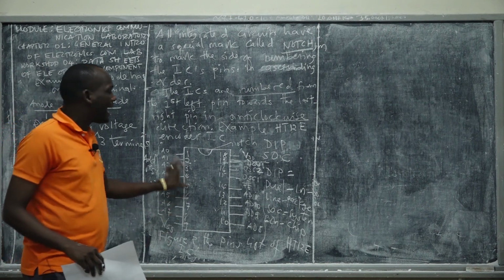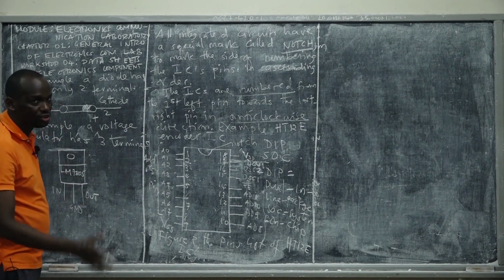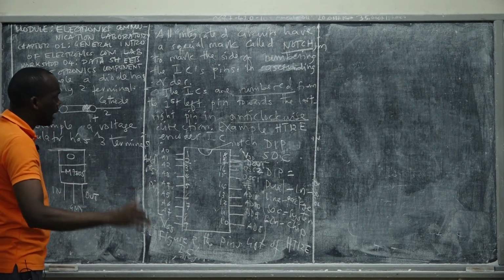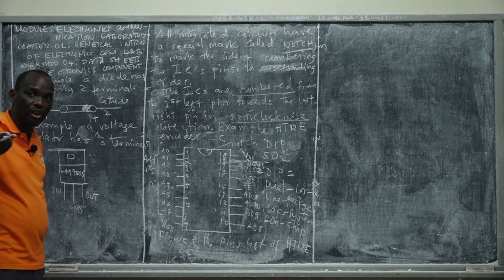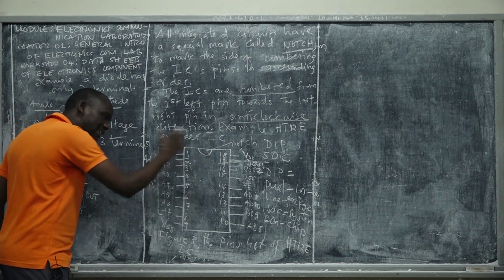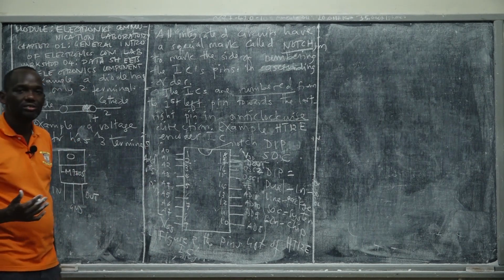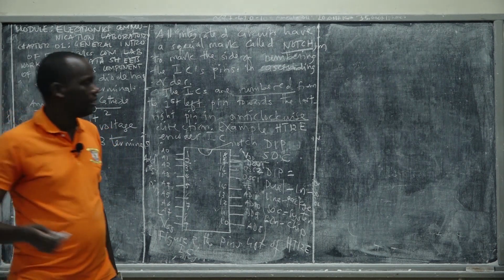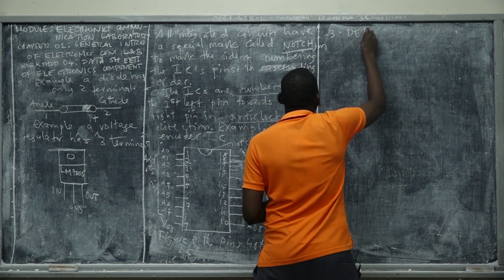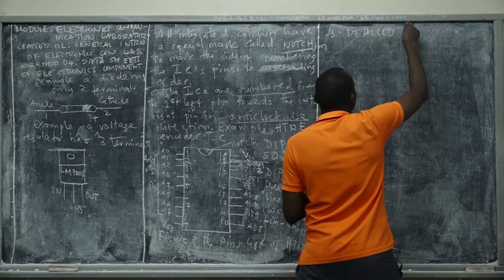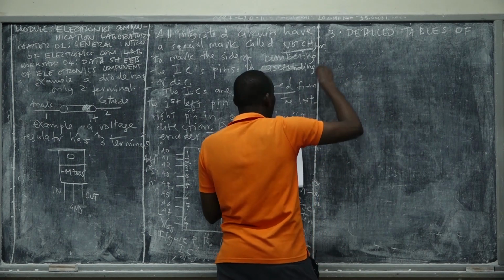Okay, so that is all about what? Because we'll be discussing this encoder later on, I don't want to touch the functions of these address pins, and we'll discuss them. We have a number of workshops discussing that. But simply remember that in this pin assignment, first you'll see the packaging of that IC. Number 2, you'll see pin numbering according to the manufacturer. Number 3, you'll see pin naming. Number 4, you'll see also the function of each pin. Are we together? Yeah. Then the next part is called the detailed tables of electrical specification.